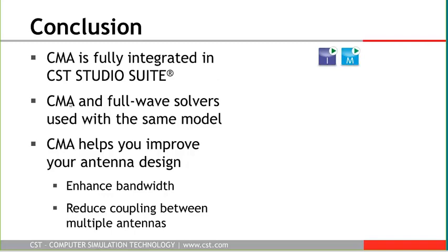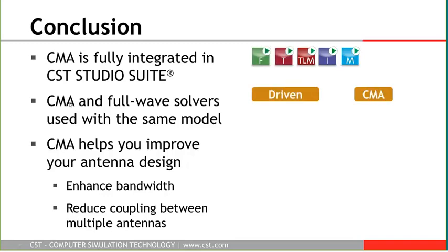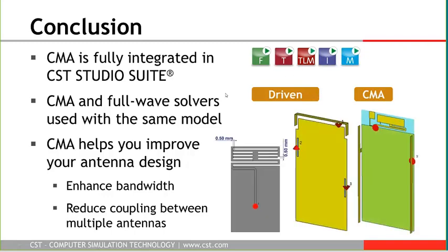Characteristic mode analysis is often, or must be, used with other full wave solvers. You have seen that throughout the presentation there was a switching between driven and CMA analysis. And finally you have seen what CMA is good for. You can improve your antenna design, you can enhance the bandwidth, and you can reduce the coupling between multiple antennas.